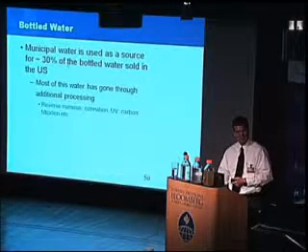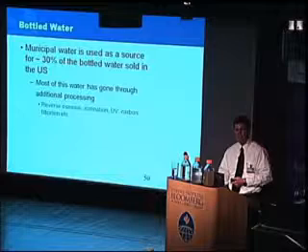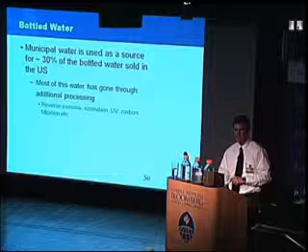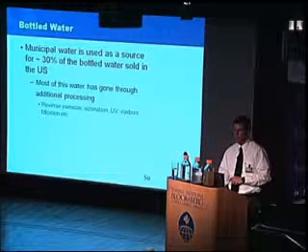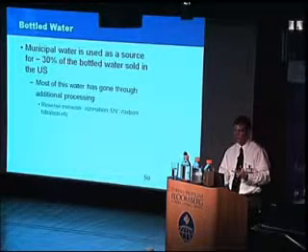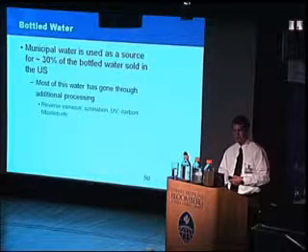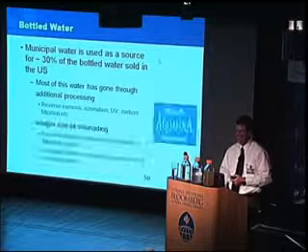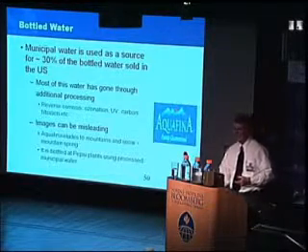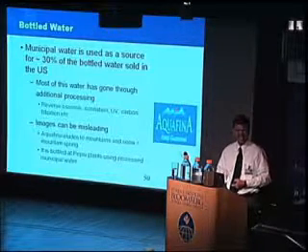Most of that bottled water comes from municipal water sources. And this number is actually increasing dramatically, that most of the bottled water from the large bottled water companies is actually municipal water that goes through additional treatment. So Dasani from Coke, and Aquafina from Pepsi, is tap water that they further treated. They do additional treatments: reverse osmosis, ozone, UV, carbon filtration. And the other thing to think about is the images can be misleading. If you look at Aquafina, it's got mountains and streams, looks like it's coming out of there, and it's this nice looking label. No, it's tap water that they further treated.